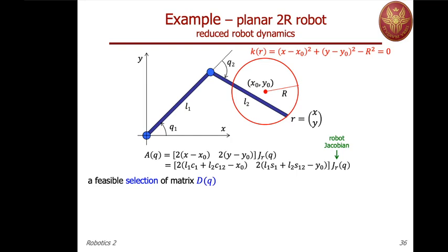If it's instead this case, the modeling will vanish exactly when we have a singularity of the robot Jacobian. But if we do this factorization, we are able to handle separately the singularity of the reduced representation, related to the choice of D, from the singularity of the robot Jacobian, which will anyway destroy a complete modeling.